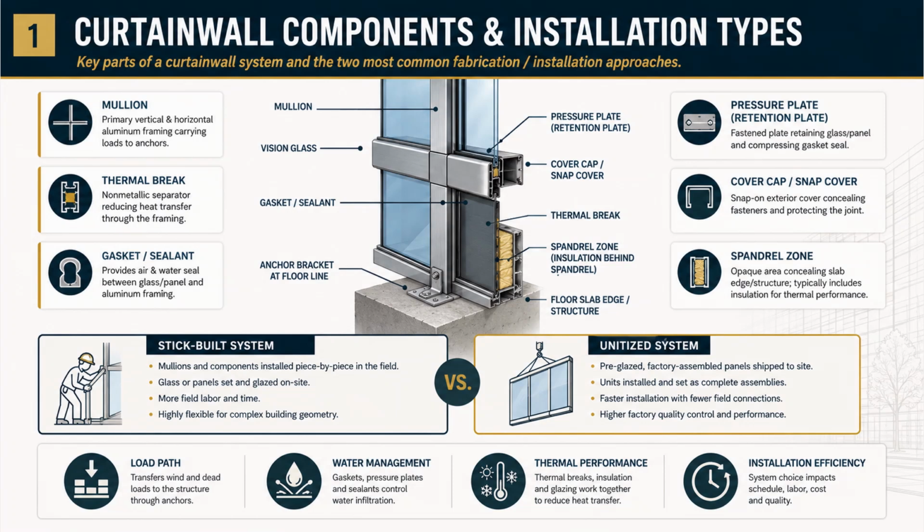Load path transfers wind and dead loads to the structure through the anchors. Water management uses gaskets, pressure plates, and sealants. Thermal performance comes from thermal breaks, insulation, and glazing working together. And the system choice affects installation efficiency, schedule, labor, cost, and quality.